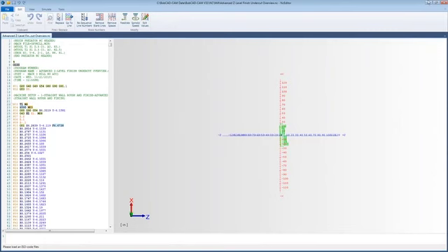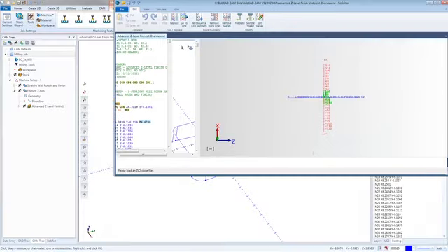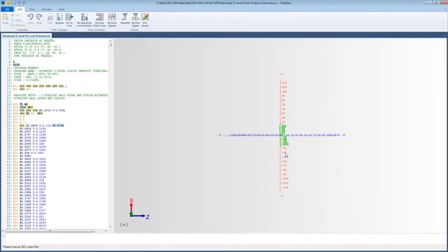If you get a problem where when you launch the NC editor, normally a big box pops up and it says initializing on it. And sometimes it'll just sit there for a minute. All you got to do is click the X on the corner of it to close it. And then a little error is going to pop up and say no license found or something like that. Just relaunch it right after that from the same code box over there, and it'll launch with no problems. It's a fix. They're going to have it fixed coming up in one of the newest builds, whenever it comes out. I don't know when it'll be fixed, but for now, just so you guys can get around that, it'll help you out a bit.